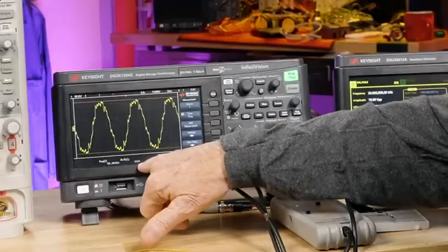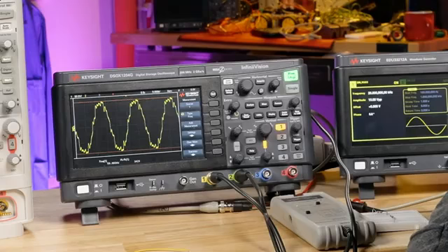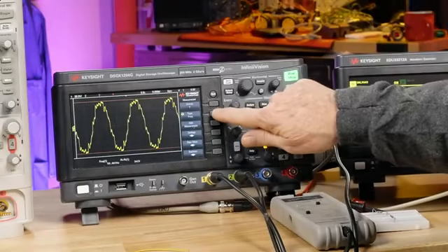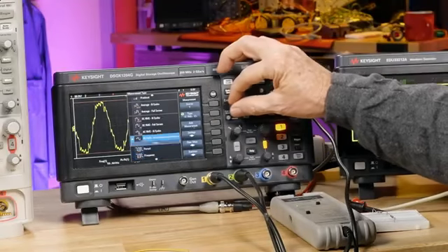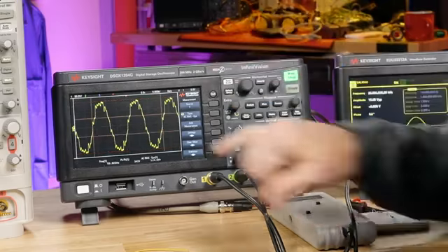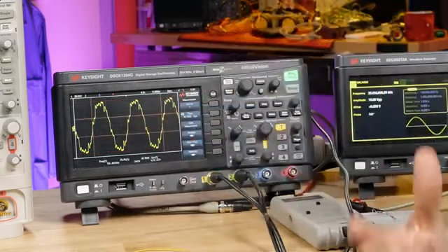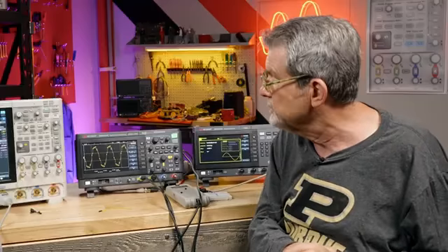The peak-to-peak voltage, it says 340 volts. Now you're thinking, in the US, don't they have 115, 120? That's RMS. So let's select an RMS measurement, and it measures about 120 volts, pretty much what we would expect.